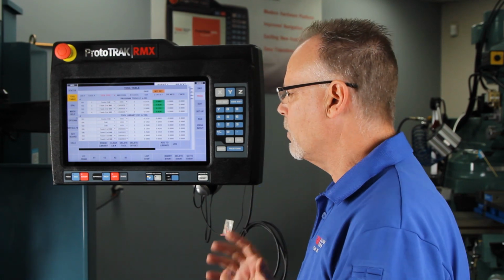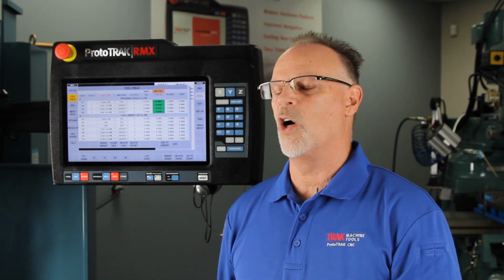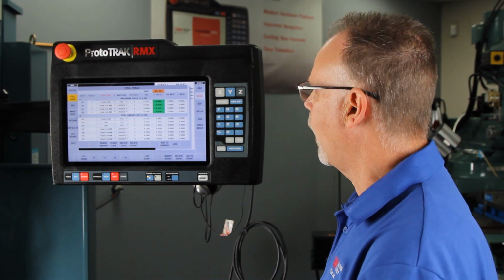Another thing I want to add to that is most of our products have electronic hand wheels. And if they have electronic hand wheels, whether it's standard or optional, there is no way to move the machine once you shut it down. So therefore, it can't have a different 0. But we do have a couple of products that have Save Temp, like our KMX product. And that one, if you don't have electronic hand wheels, somebody could actually move it, maybe cleaning the shop or something. So always pay attention to that warning so that you don't make that mistake, okay?